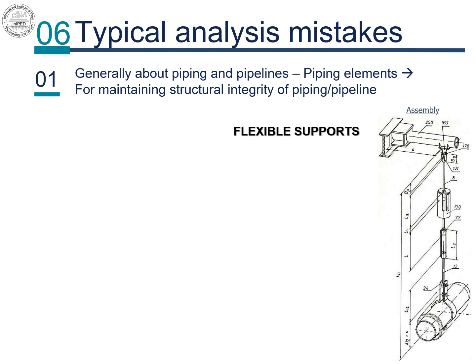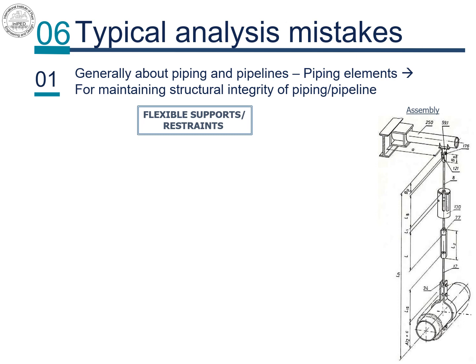With flexible supports, movement of the pipe is not restrained, but rather controlled. Flexible supports are designed around a flexible device, a spring, which enables the pipe to move while still providing support to the piping. In simplest terms, the advantage is that, if designed properly, the pipe unrestrained in movement will exhibit much lower stress than a fully restrained one.